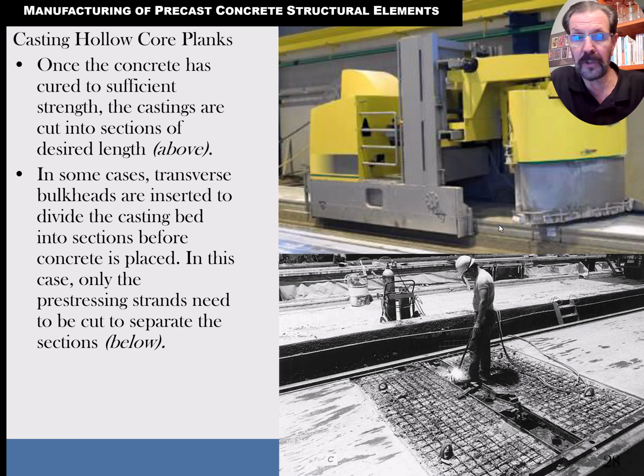and that's really important when you're dealing with zero slump concrete. We do that with the concrete masonry blocks also, zero slump mixes usually. If there's a cavity or a bulkhead like with double T's, we do this all the time. We'll have a bulkhead in here, and there'll be a cavity that they'll literally use a straight-armed cutting torch and reach in there and cut the cables, cut the strands, the pre-stressing strands.